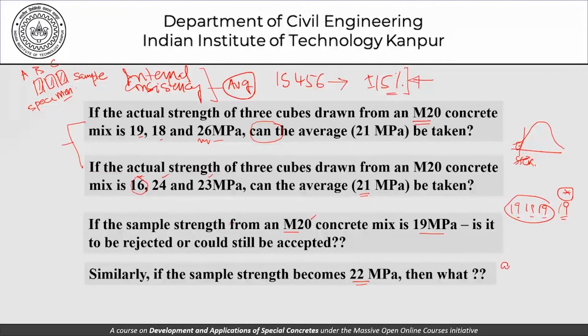What we talked about in the previous discussion was something which is automatically unacceptable, that is automatically rejected. And here we are talking about automatic acceptance with just one side or the other of the characteristic strength. So this question we need to answer when it comes to acceptance is a very, very important part of our understanding in terms of properties of hardened concrete. Of course, the fact that it has a strength, yes.